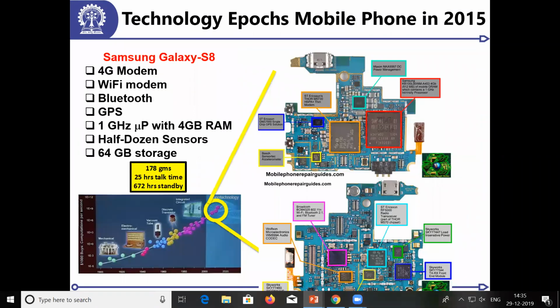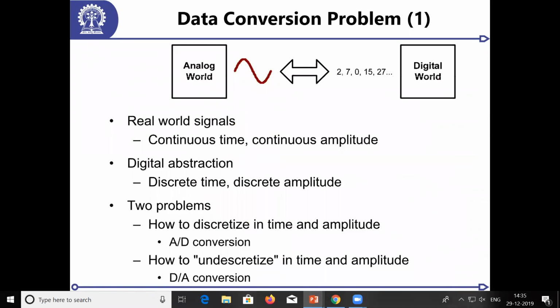So now, as I said, I'll give a brief overview of ADCs. So you have the analog world, and there is a digital world, and we do processing in the digital world. And there is an interface, the ADC, which converts from analog to digital, and vice versa, because you have to control something in the outside environment. You have to convert from digital back to analog.